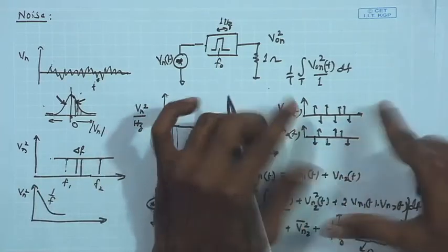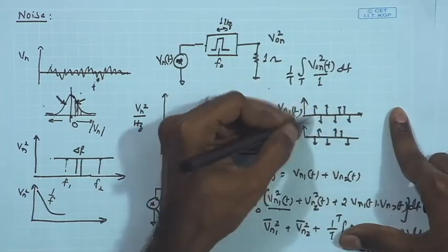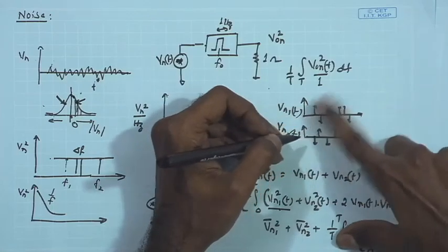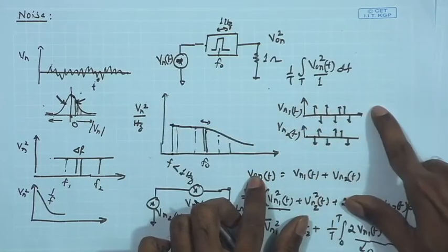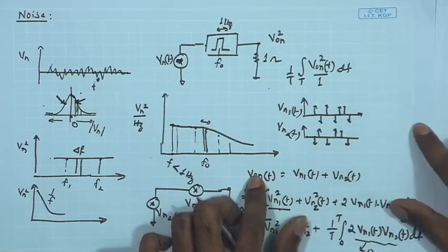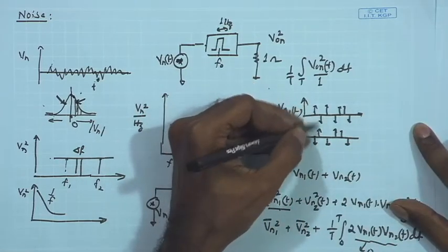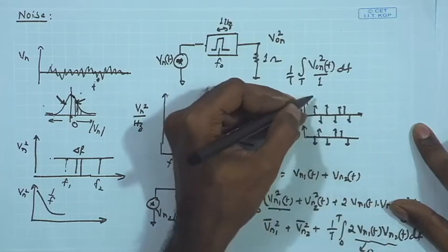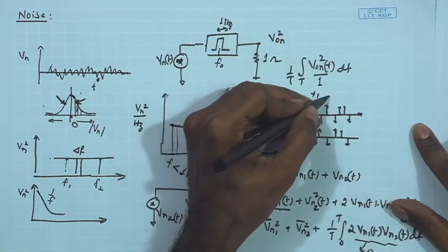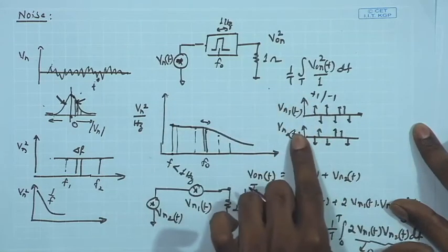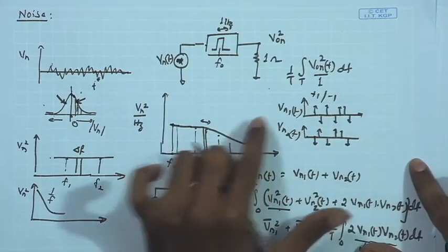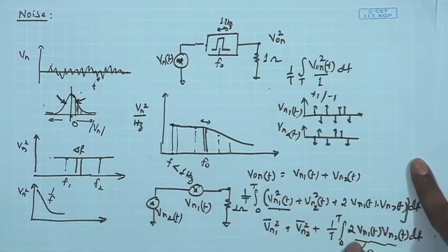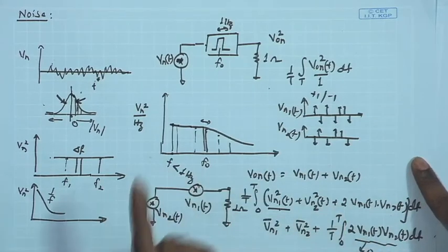And if we multiply these samples together, the probability of getting 1 and -1 at an individual point is also going to be equal. So, if I multiply these individual noise samples at these locations, I am going to get +1 or -1 with equal probability, and then if I sum all these together, the value Vn1(t) times Vn2(t) integrated over this entire period will again vanish.